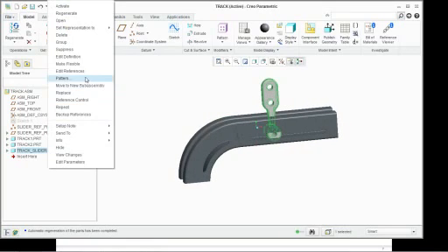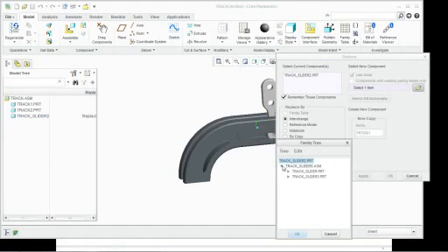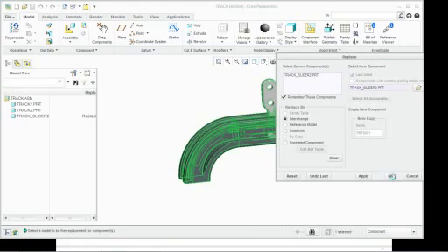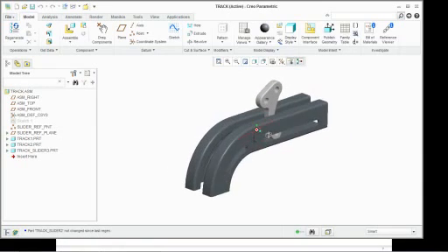I can go in and just simply replace using an interchange again, click open, and this time pick maybe that track slider 3, and click OK again. And when I click OK, notice now it's changed to that other kind. Well, that's fine and dandy. Do I have to go back and make a new interchange every time I add an assembly, delete them all off, and add new ones? No, it's really quick and easy to go in and add new parts to an existing interchange.